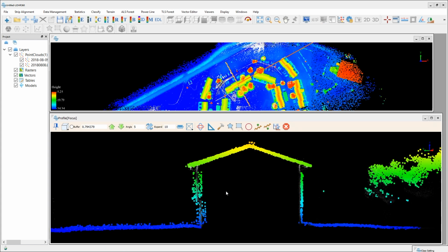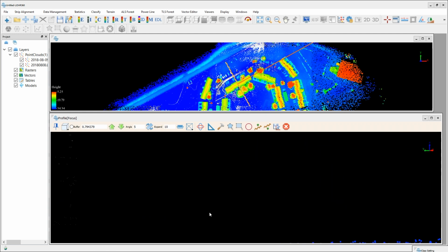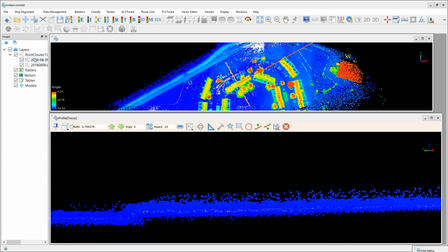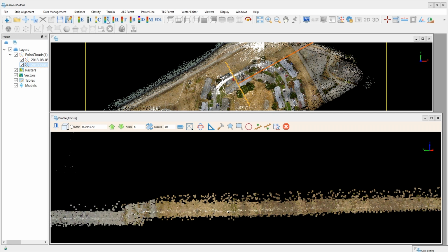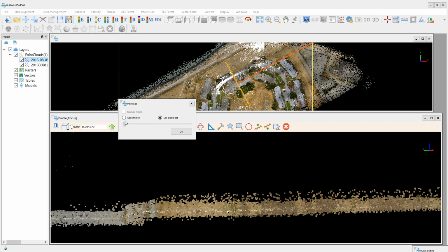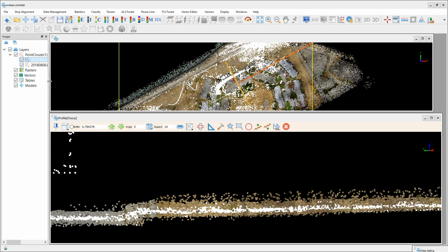What I want to do next is adjust the display properties of the transformed live backpack data set to make them easier to view. To do this, I will select to turn my UAV data set into RGB, which is available because our LiDAR system has an integrated color camera sensor, and that photo information was then fused with the individual LiDAR point cloud during the georeferencing step of post-processing.